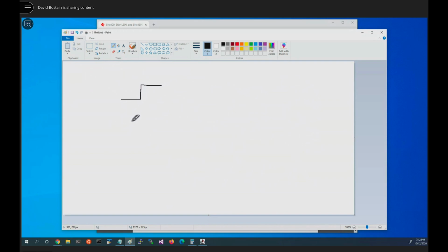I have another signal which I want to be latched into something on that rising edge. Now, in order to do that, my other signal can't change at exactly that point in time. If it does, I might or might not see the signal. I might latch in the wrong value.